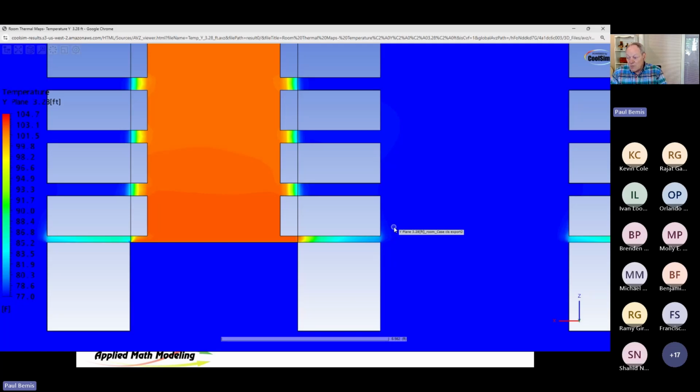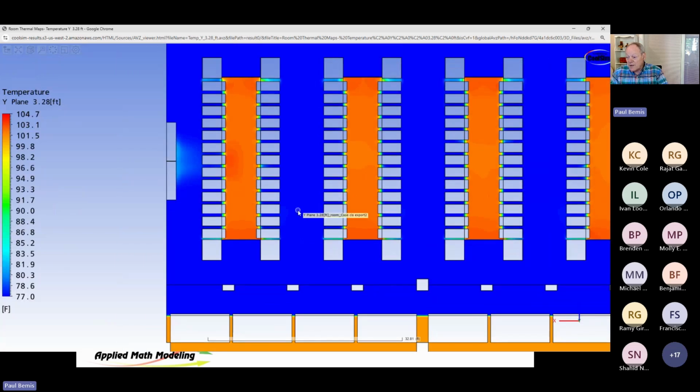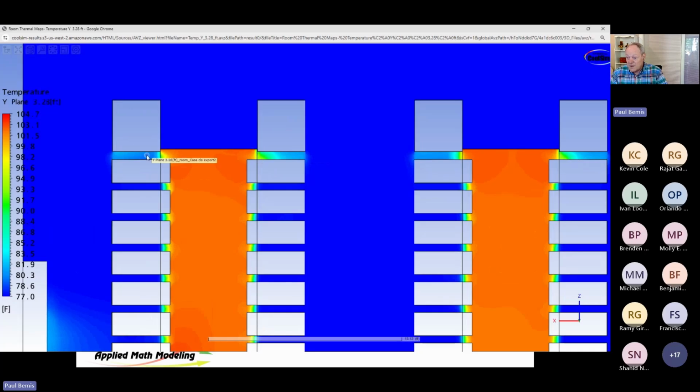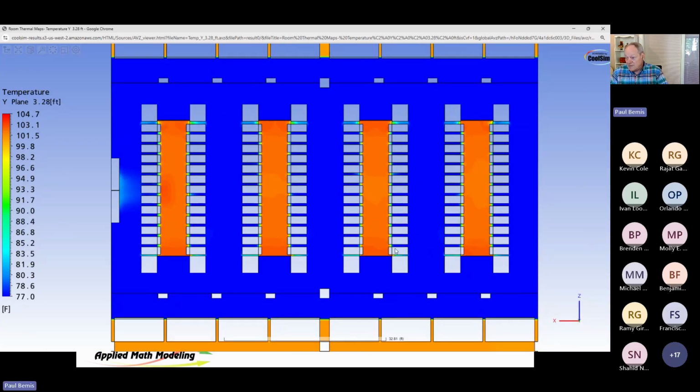High velocity air is low pressure air. Remember, velocity and static pressure trade off against one another. The lower pressure here caused by the high velocity is pulling. There's actually a pressure delta pulling the air through the membrane. Okay, and it varies depending where you are. Up here, it doesn't look good. I mean, that one looks like it's leaking. That's why you're getting those conditions. Now that's steady state. I mean, everything's working perfectly here.